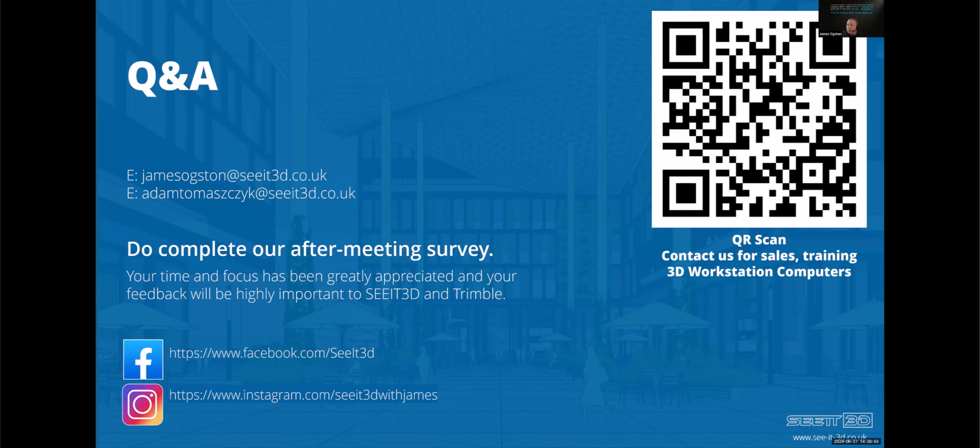I think also, Adam, when designers are downloading models, they're doing that to populate a scene, so they're expecting the models to be lightweight. Unfortunately, depending on what they download, you really need that little bit of extra core knowledge to say, right, I'm going to check this model. Is it good? Is it not? Do we save it? You double check that it's lightweight, check for hidden geometry. So the answer is, it depends.